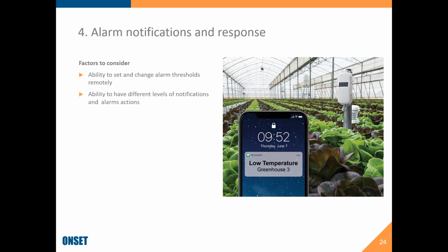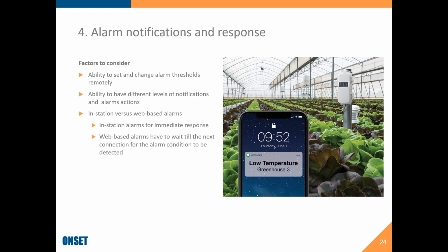And it's also handy to have different levels of alarms. You might get an alarm to notify the guys in the field to go check something out at one level, but if the temperature gets above that or below that, you can notify the manager. You might want to know at that point.